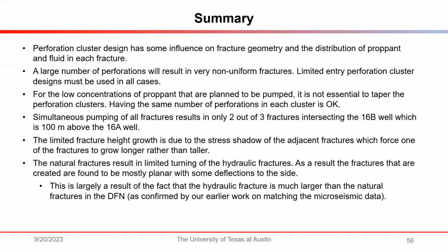So perforation cluster design has some influence on fracture geometry and the distribution of proppant and fluid in each fracture. You can redistribute fluid and proppant more efficiently by varying the number of perforations in each cluster. The large number of perforations will result in very non-uniform fractures.